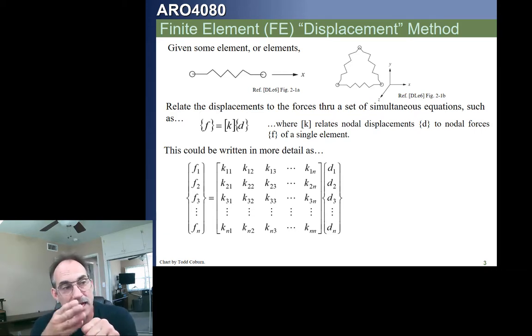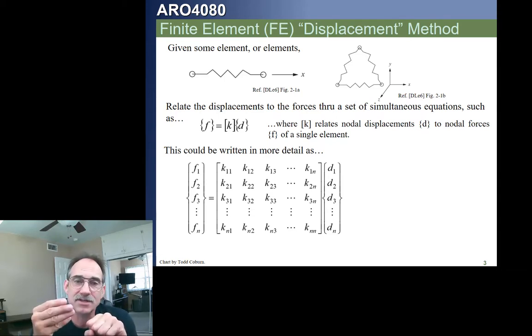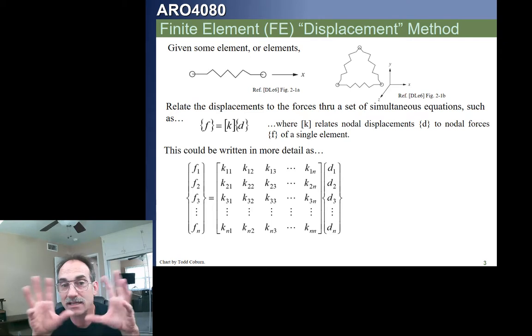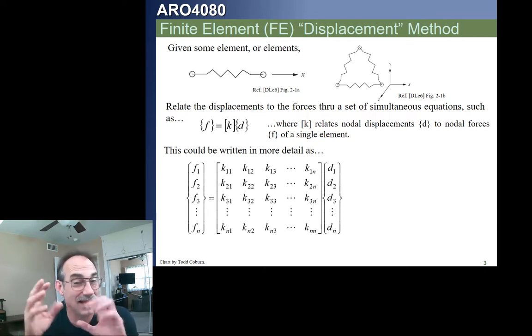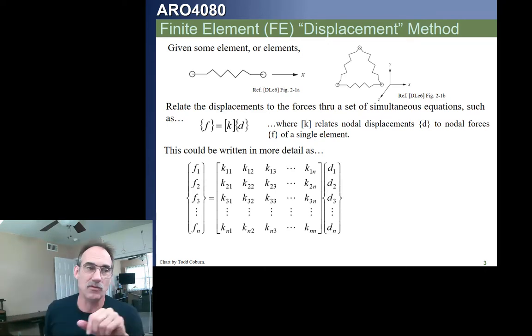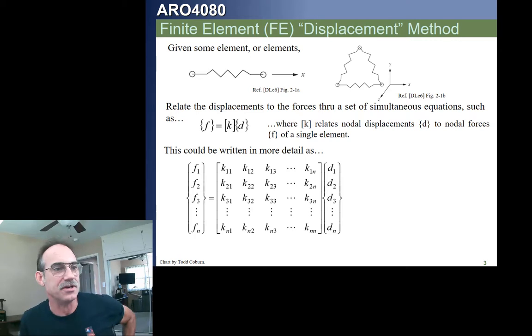So we see, if we look at that column to the right, displacement 1 at node 1, displacement at node 2, displacement at node 3, these displacements, and here we're talking about a linear system, are a function of all the elements that attach to the node. Any elements in the model that don't attach to the node will have a zero stiffness for affecting that node. They may have a stiffness to affect other nodes. Okay? With these ideas in mind, we're ready to move forward in our discussion.